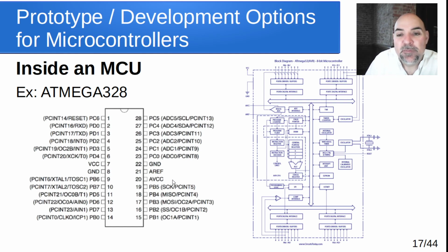And so what you do is you basically configure this chip. It has some programming to configure the pins, whether you want them to be just I/O, and if it is I/O, is it input or is it output? Does it have an interrupt associated with it? And then it has alternate functions for those pins, some of which have multiple alternate function options.